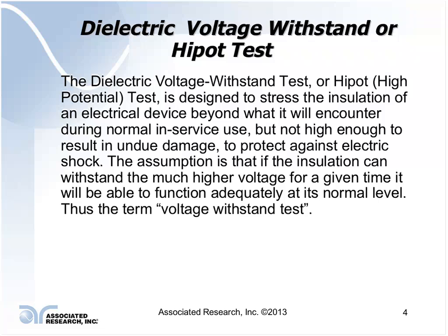Well, with many of the test samples done on products, we take them to the point of failure, where we've determined at what level the insulation will break down. Then we rate that material to operate at a working voltage or stress that is much lower than that breakdown potential. This is how we grade insulating materials.